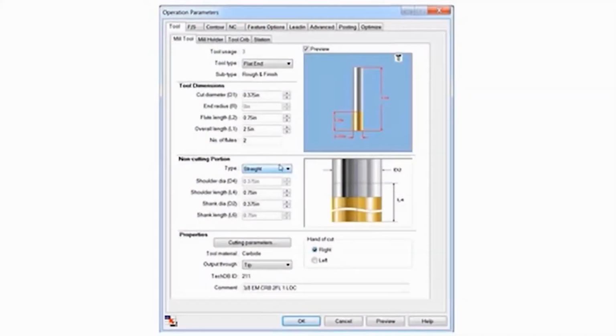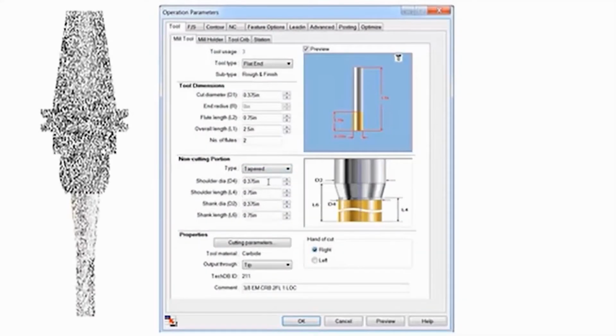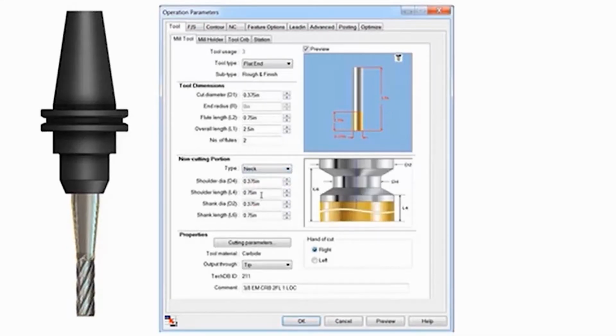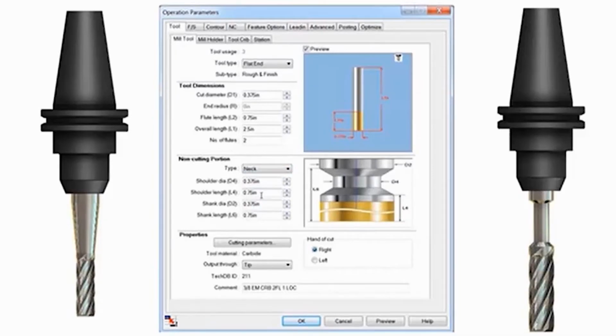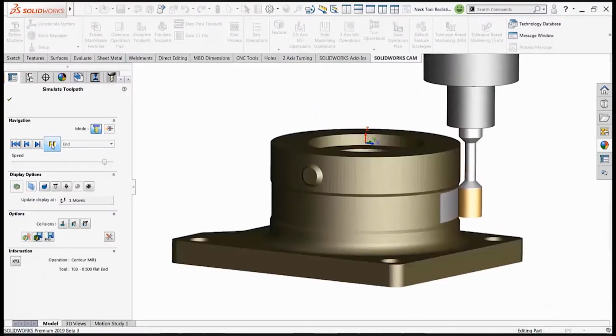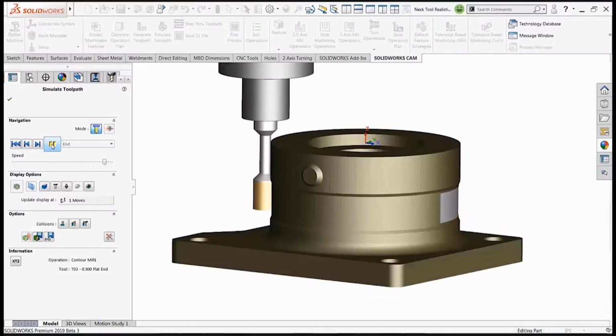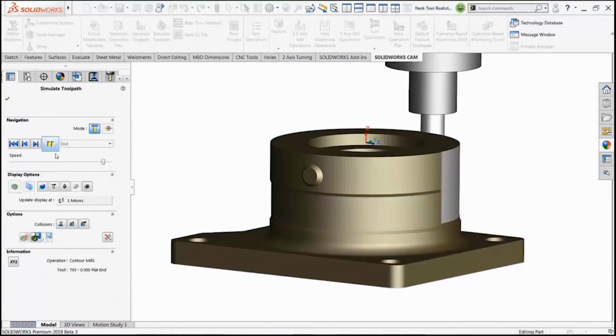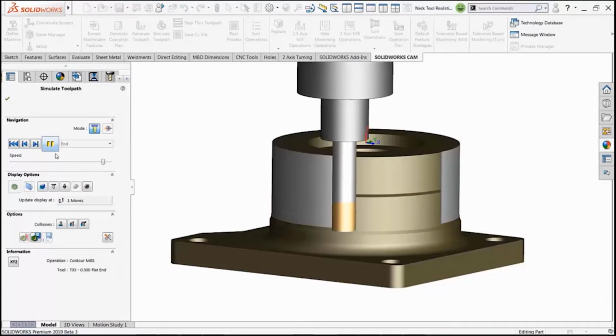In the past, the only time you could see true tool shape was with custom cutters. However, a lot of standard tools have other shapes, and who wants to literally duplicate a standard library? With SolidWorks CAM 2019, there's the availability of neck and taper options, so you can simulate the cut accurately, without the guesswork. No more watching your simulation cut away the upper portions of the part.